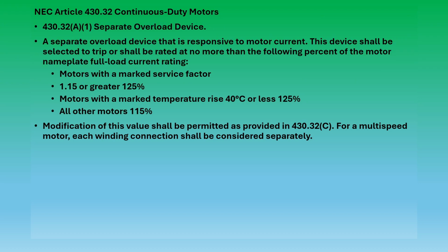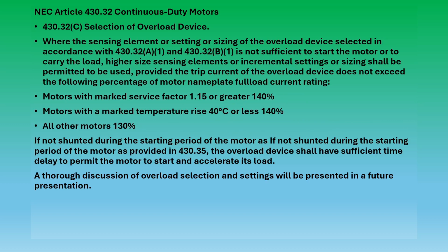Motors marked with a service factor of 1.15 or greater is 125%. With a temperature rise of 40 degrees C or less, 125%. All other motors is 115%. So if it's a service factor 1.0, it would be 115%. Modification of this value shall be permitted as provided in 430.32(C) for a multi-speed motor. Each winding connection shall be considered separately.